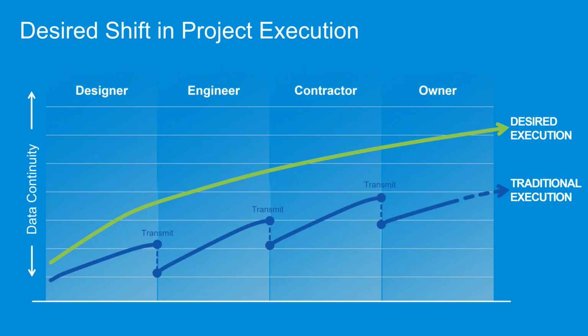Once you move on to the BIM 360 platform, you have proper communication across designers, engineers, contractors and owners. If you look at the graph, communication is always high, with live collaboration, and everyone internally and across stakeholders has the latest version in their hand. We also have proper permission levels. Not everyone will have access to all the project files, so we can set up permission control that is role based, company based, or even at the user level.